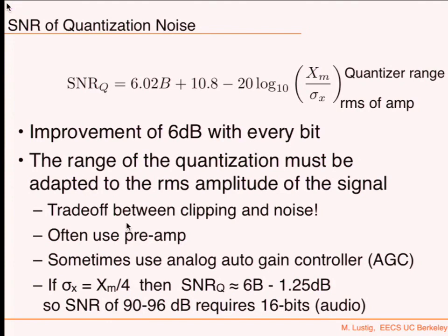So you can think of a case where, first of all, you need a preamp in order to amplify if my signal is really too low for my ADC. So every ADC quantizes a certain voltage into bits. So if the range is 2 volts, plus minus, for example, then I need to make sure that I amplify it to that range, or I attenuate it to that range so I don't get clipped.